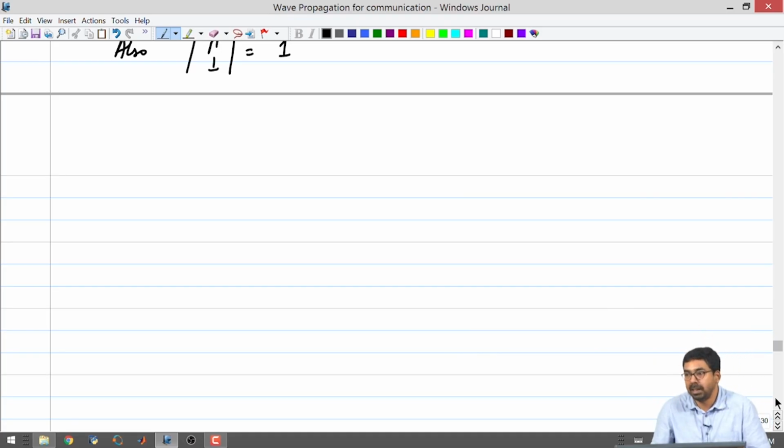You may have to calculate gamma parallel and gamma perpendicular for the single case, and then we know that the electric fields overlap and can be superposed, alright. It follows the theory of superposition, it is a linear term, you can add electric fields in a quantity. So, that means you will take gamma parallel, gamma perpendicular, etc., calculate the reflected electric field for both these polarizations, and then add them together to get the net electric field that is being reflected. Okay. So, that is one thing that we have to remember.